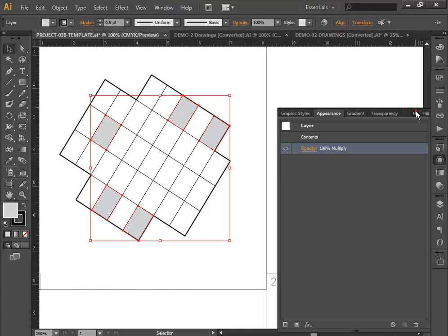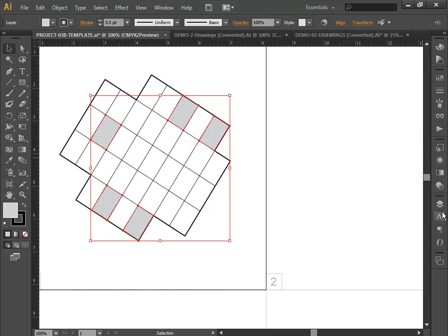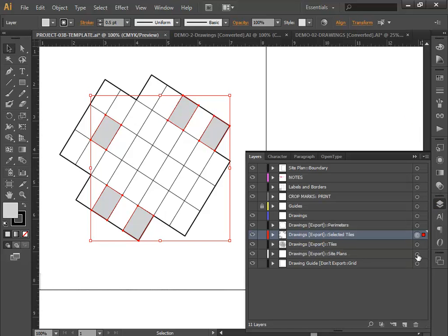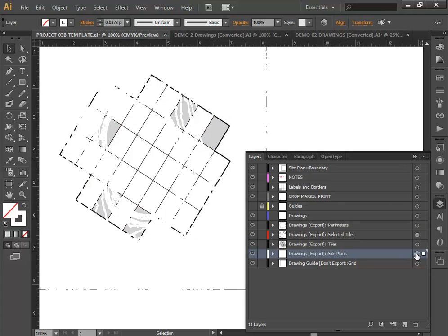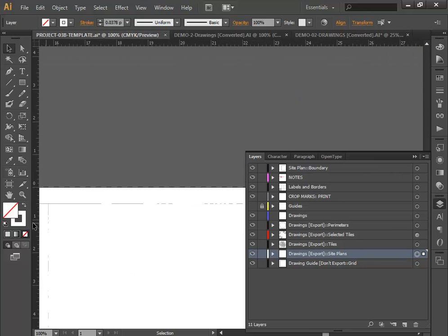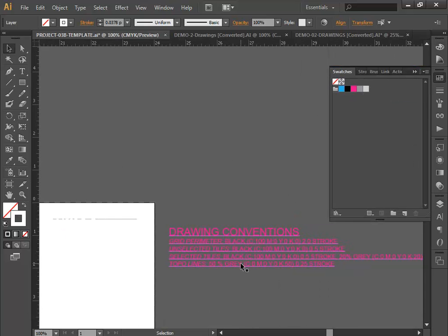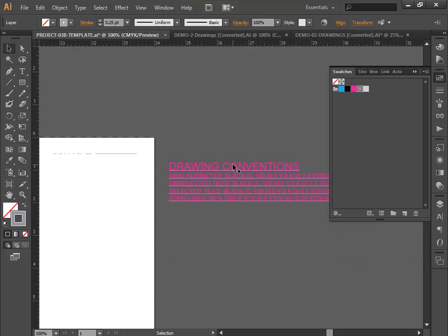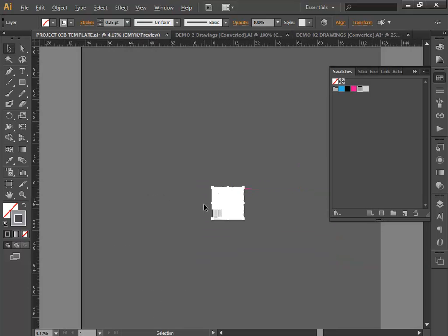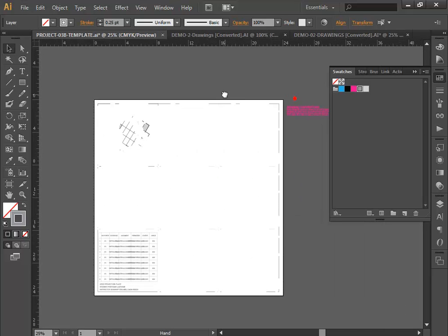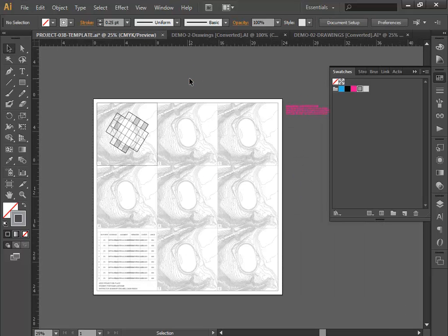The last information I've got to do in terms of the actual drawing is the site plan layer, which has the topographic information on it. Right now, it's this white color. Those topo lines are going to be a 50% gray color with a quarter-point stroke. There's a lot of them. They're going to be nice and light. They're selected right now on a white layer, so that's why they're not showing.